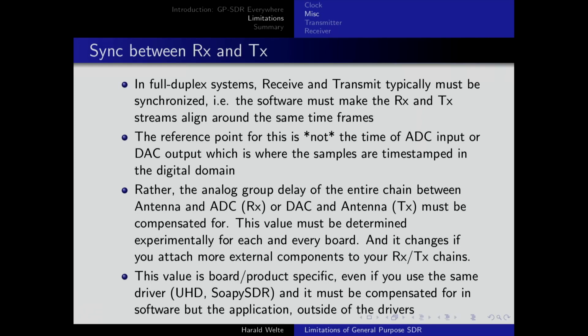which means that you need to be able to relate the clocking of the receive and transmit samples. And you need to know that a certain moment in time represents the receive signal at the antenna input and not the receive input at your ADC. So you have your antenna input, and then you have some low noise amplifiers or whatever kinds of blocks, even PCB traces, which all cause delays in the signal propagation.